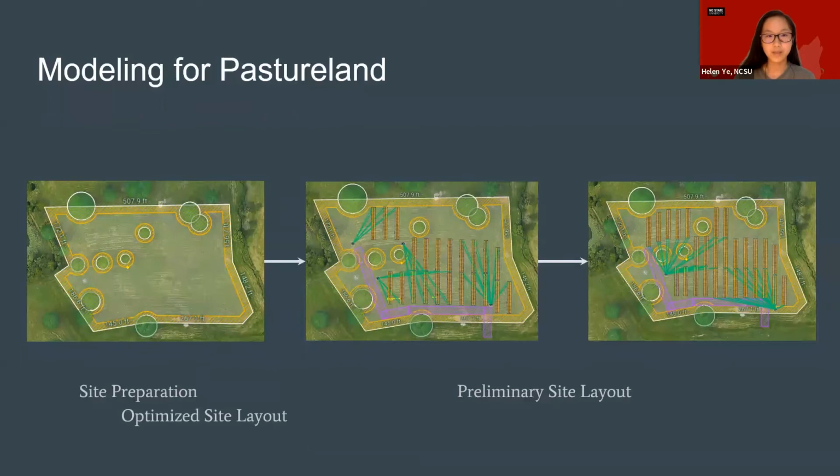After the initial placement, we moved on to optimizing our layout design. Spacing between panels was decreased until shading presented in the panel and the row behind current panels when tilted on winter solstice. Our final ground cover ratio was 0.5.